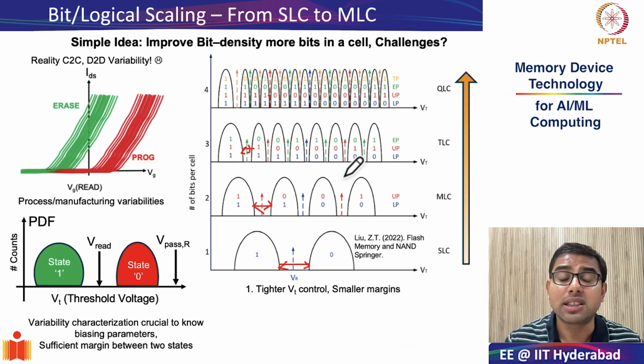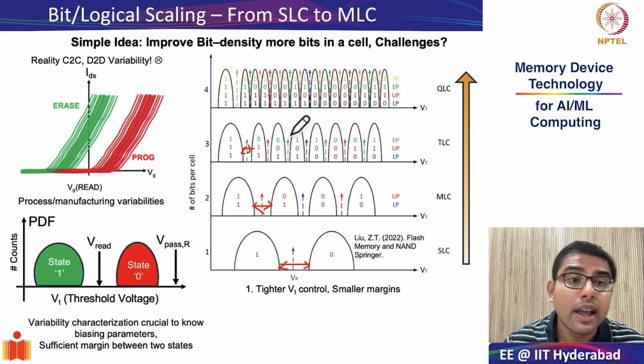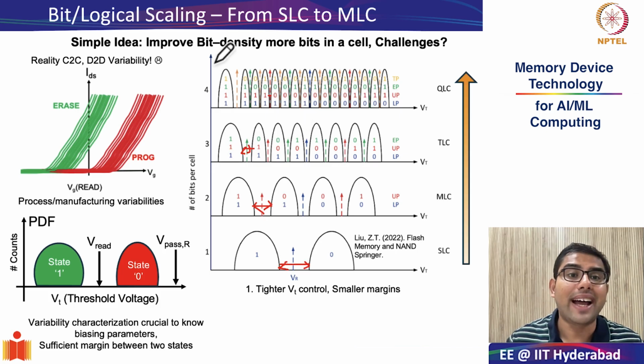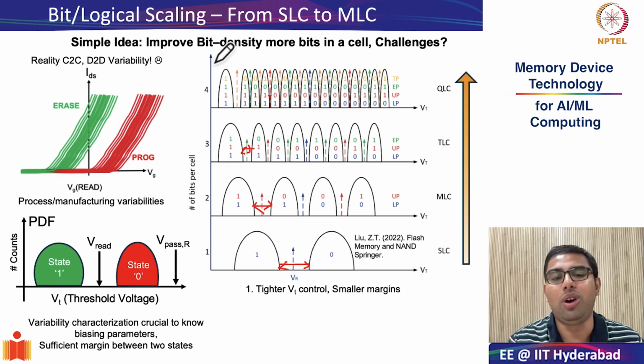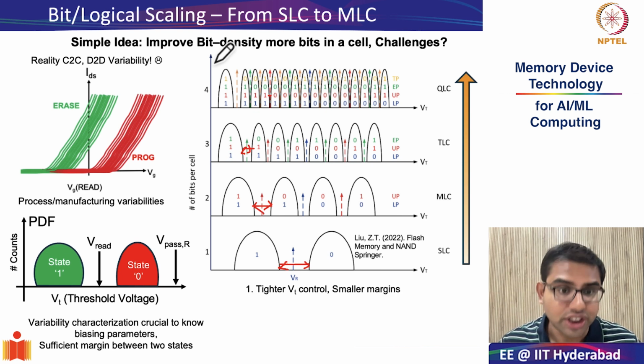When the margins become much smaller, you have to understand that when you program and erase these particular states, especially when you program states other than the erase value, other than the lowest threshold voltage value, you have to be very careful. You need a very tight control in the threshold voltage programming. How is this done? We will see later on in this very lecture.